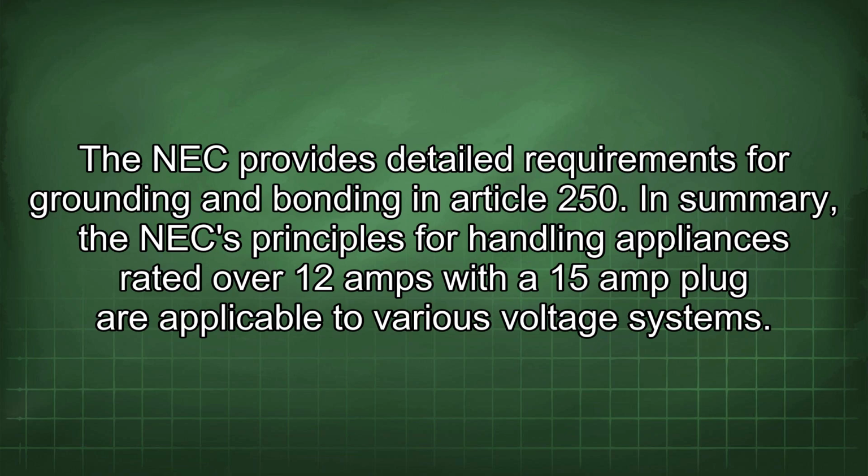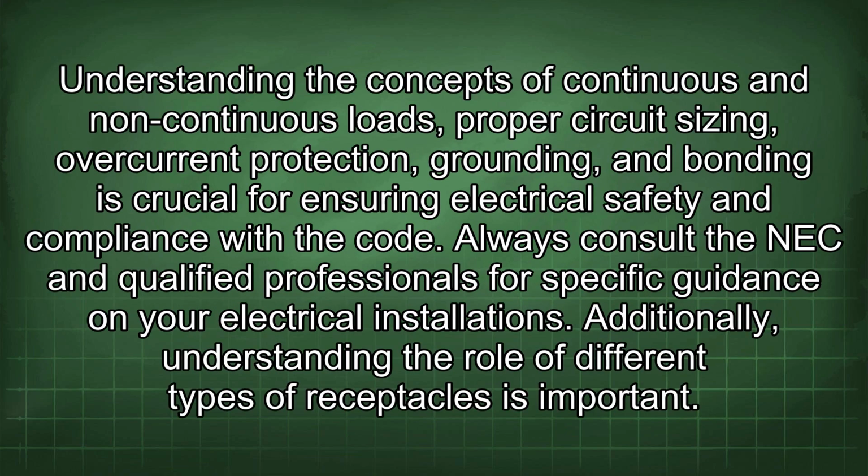In summary, the NEC principles for handling appliances rated over 12 amps with a 15 amp plug are applicable to various voltage systems. Understanding the concepts of continuous and non-continuous loads, proper circuit sizing, overcurrent protection, grounding, and bonding is crucial for ensuring electrical safety and compliance with the code. Always consult the NEC and qualified professionals for specific guidance on your electrical installations.